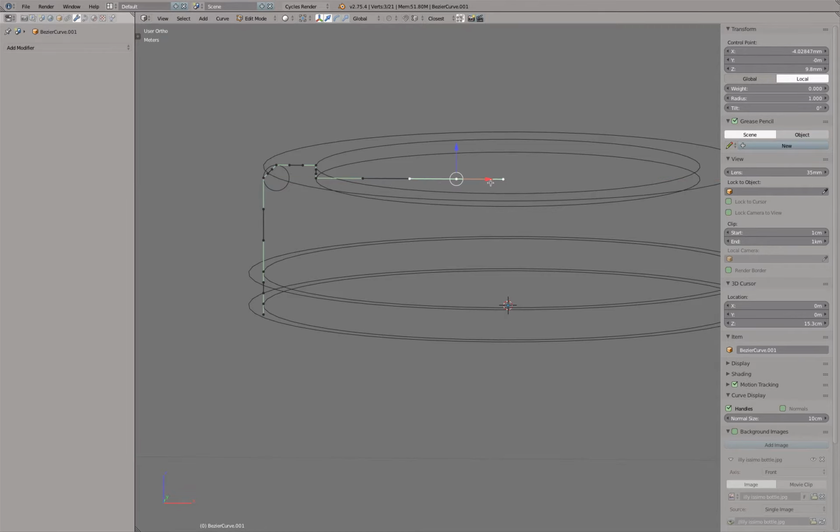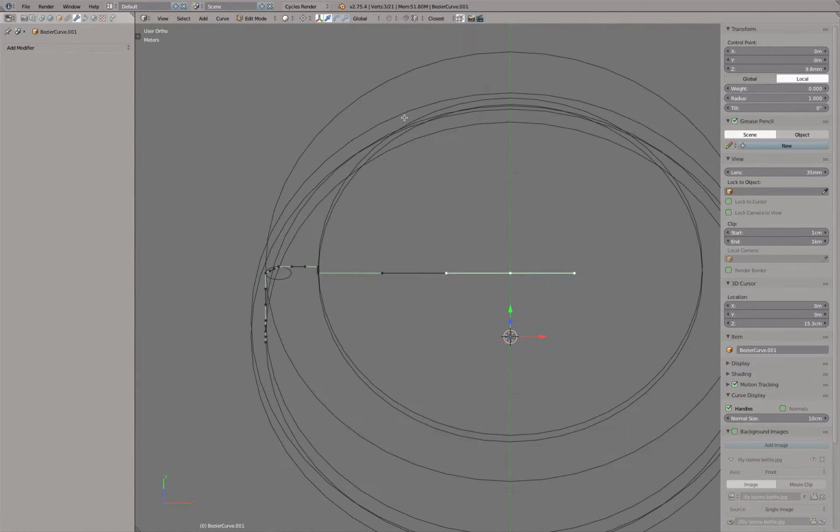How do we find the midpoint? That's actually where our 3D cursor comes in handy. Set to 3D cursor, and then we could say SX, so scale along the z-axis to 0, and it's centered. There you see it. Let's do this one more time.